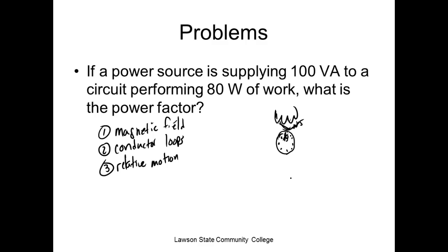So a single-phase motor would never run. It would just sit there and hum. So to make a motor run, one of your fields has got to do what? It's got to shift. So with three-phase, we don't have that problem. In a three-phase motor, the fields are out of phase. So when this one starts dropping down, this one's coming up, and it causes the field to do what? To rotate. So with three-phase motors, we have no problem.